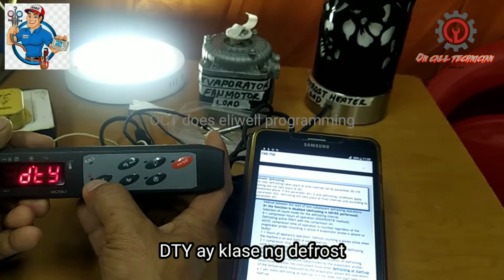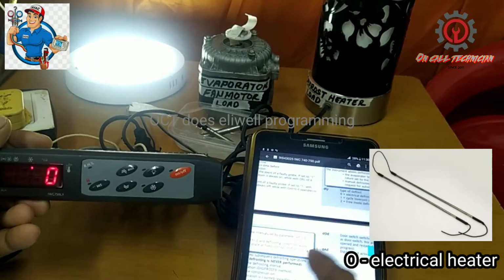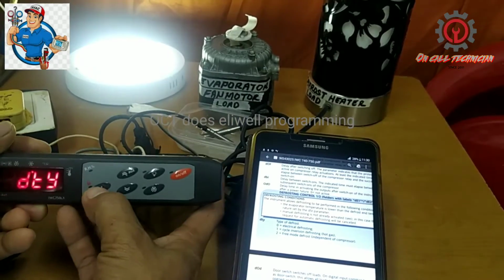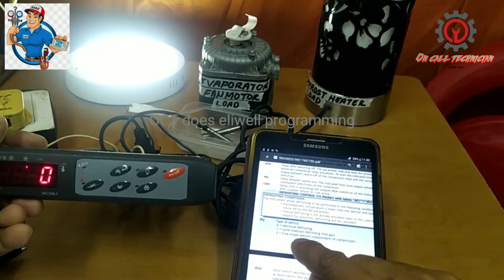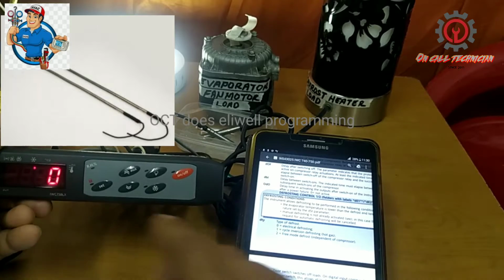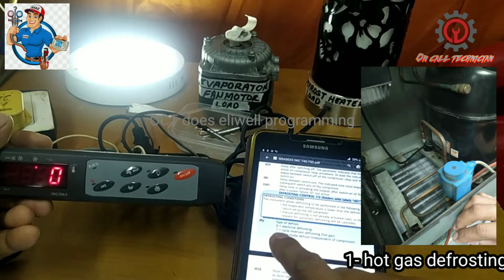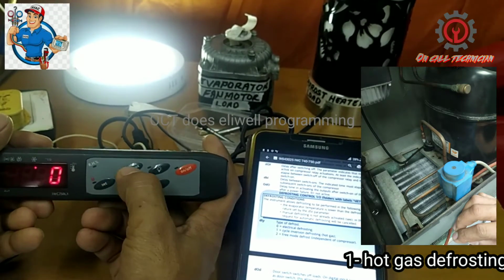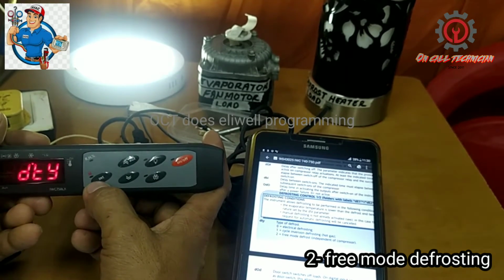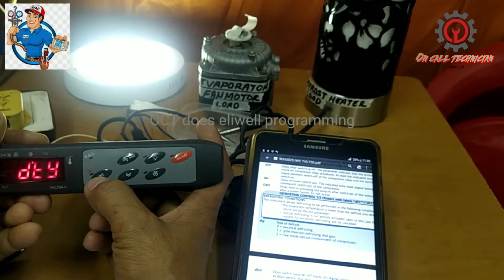Okay, press this set, and the value is 0. Now the DTY. Okay, here DTY guys is the type of defrost. If you want electrical defrosting, just press 0 or select this 0. If you want inversion defrost or via hot gas, you select 1 like that, then set. Now if you are using electrical defrost, just leave it to this 0.